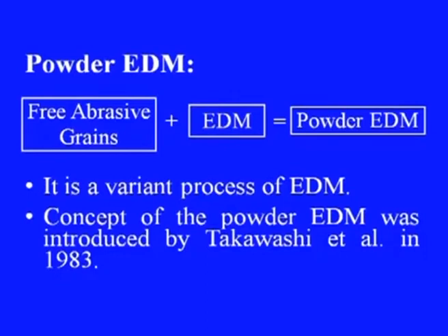As we know, in EDM the material removal mostly takes place in the form of erosion of the work material due to the cavitation effect as well as thermal melting and evaporation of the material due to the high frequency sparking. The concept of this powder EDM was first introduced by Takahashi and his group of researchers in the year 1983. Thus, it is relatively a new process.